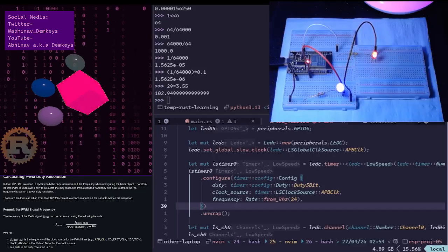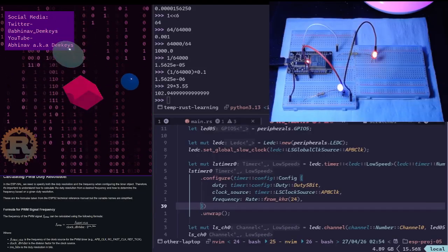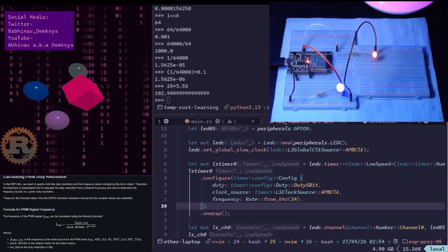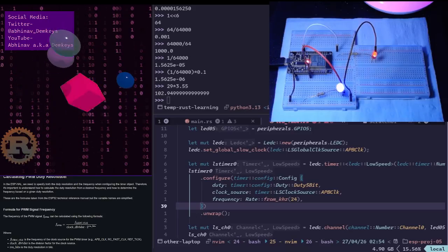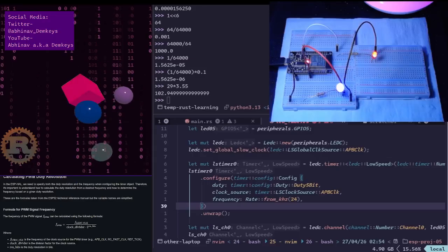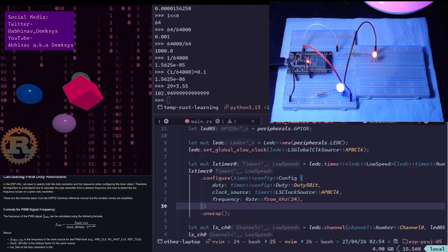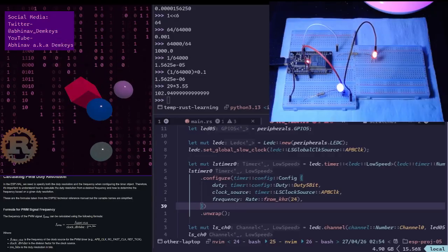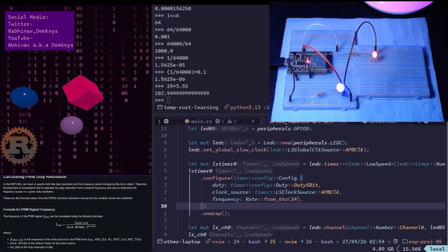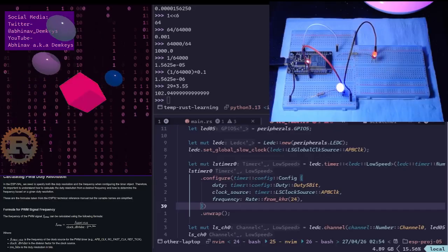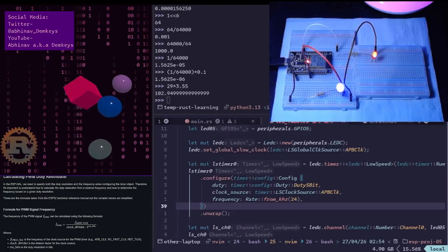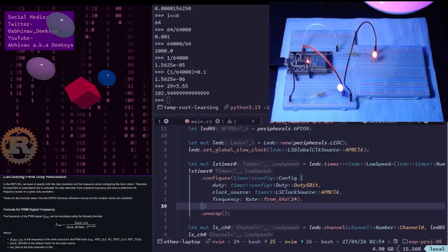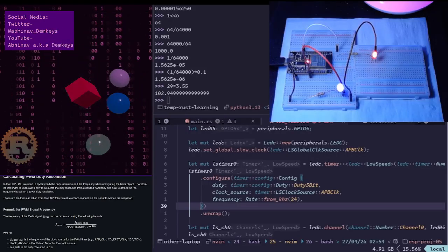It turns out that LEDC is the general purpose PWM, even though it says LED, it can be used for various things. And then you have motor control PWM, which is much more geared towards motors. But I'm sure, given its working, you are not limited to motors if you have a very specific use case that just so happens to fit the way motor control PWM works. Then you can use it for that purpose.